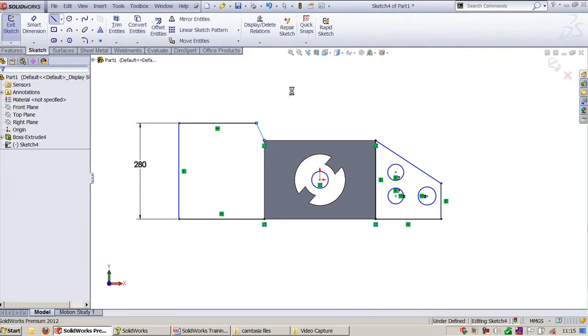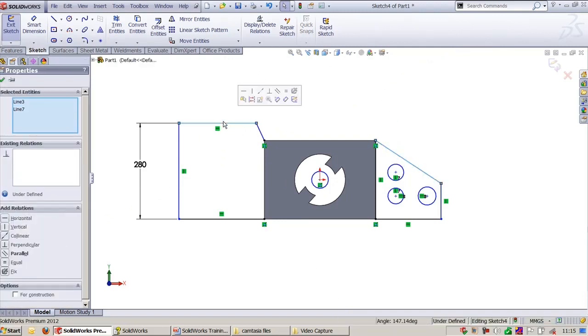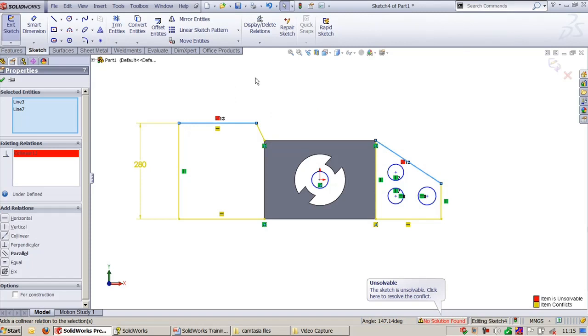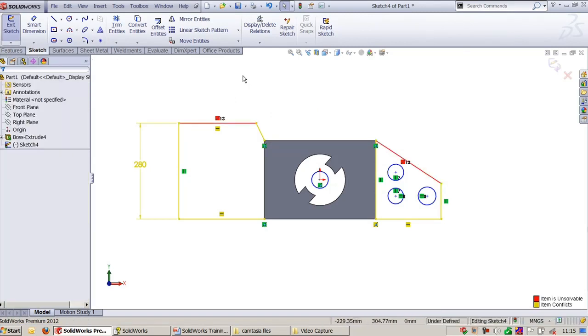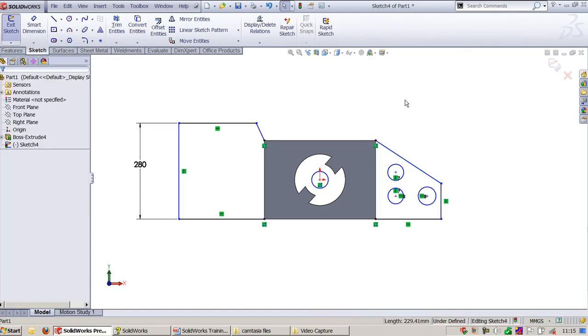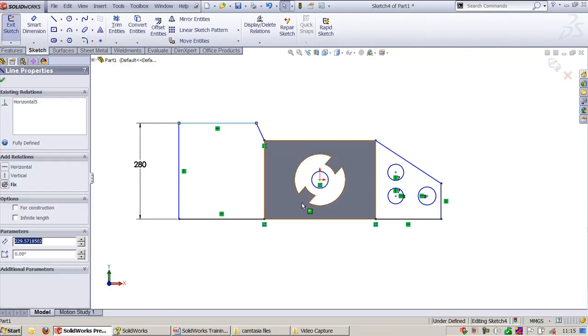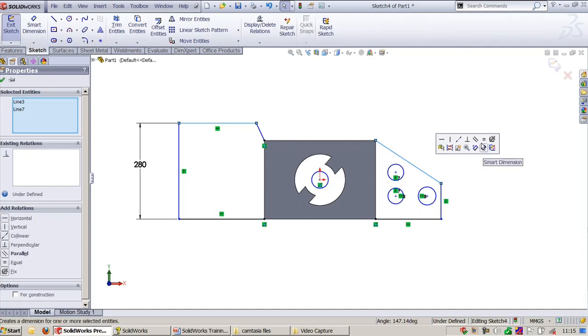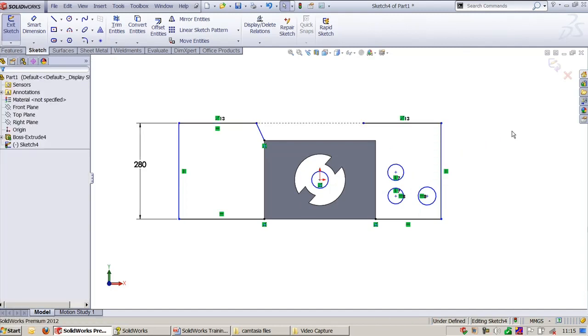But now what is my requirement is I need to make this line segment and this line segment should be collinear. Now once again there is an issue. What I will do here is I will cancel this, and we have to remove this one since it is having the relation with the endpoints. Now definitely it should work out. I'll select these two line segments and I'll say collinear. Now you can see both will be lying on the same plane.